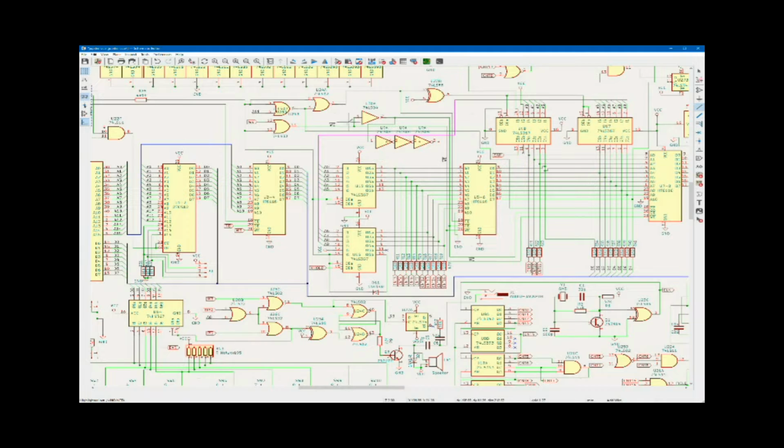So now what we've got is this write enable, and it goes through 4 inverters. If you go through 4 inverters, you're going to get back exactly the same thing that you started out with, because every pair of inverters sort of cancels out. But each inverter is going to add 20 nanoseconds, another 20. Now we're up to 40 nanoseconds, now we're up to 60, now we're up to 80. So we're going to delay that write pulse by 80 nanoseconds.